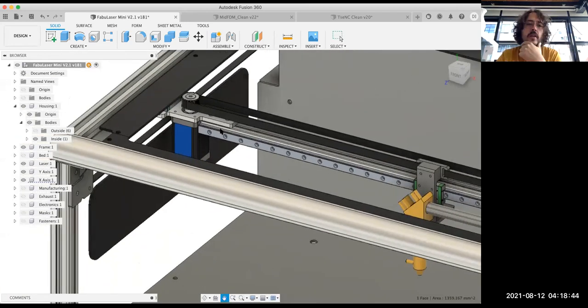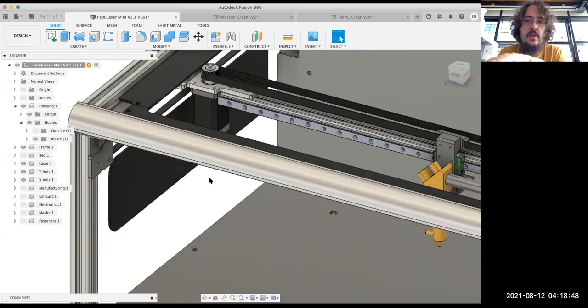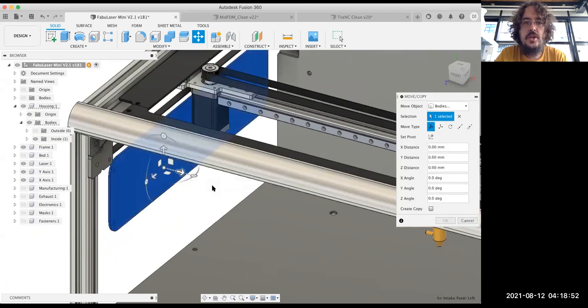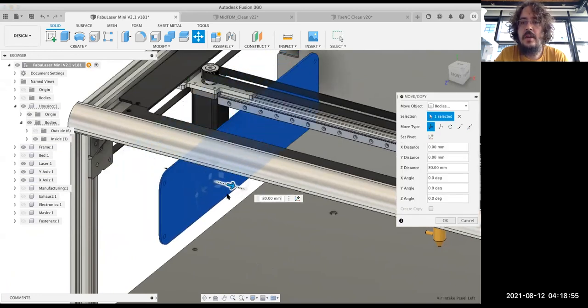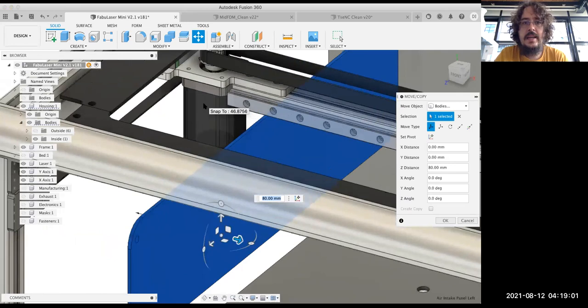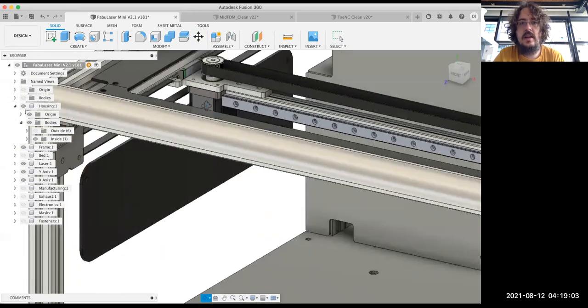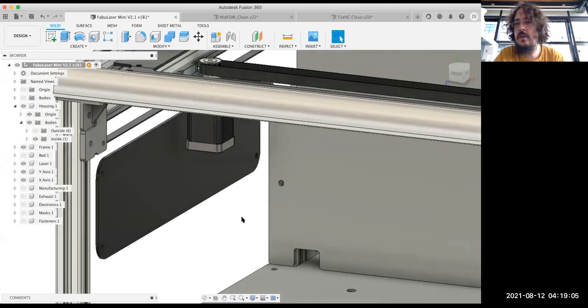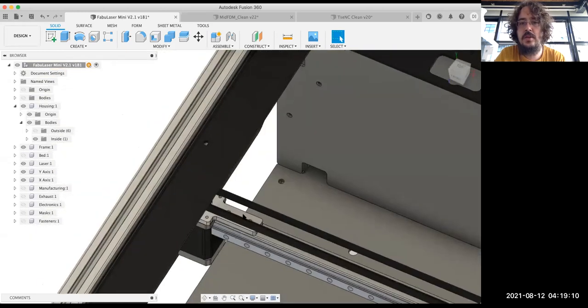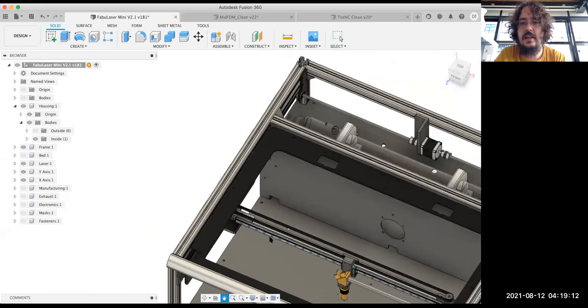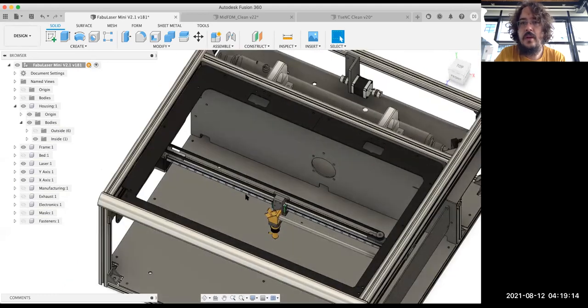The one thing that is worth mentioning in comparison to a standard laser cutter is that this saves a lot of cost, because usually laser cutters have an inner structure standing somewhere here, which has the motor and the electronics and many other things on the side. By putting the motor directly inside, I avoided having further inner boxes inside the machine. Everything is integrated for the motion of the x-axis inside the laser cutting chamber here.